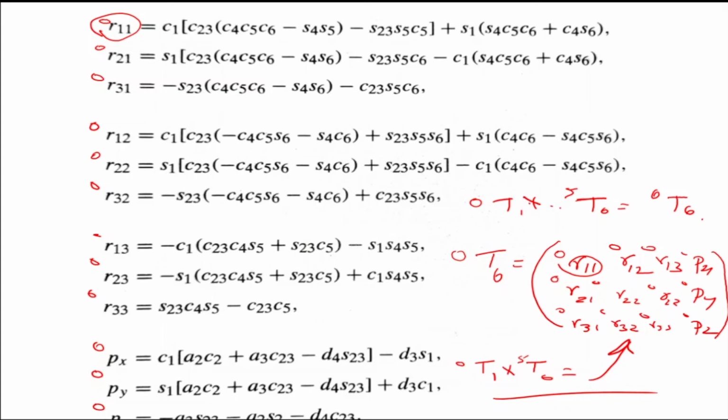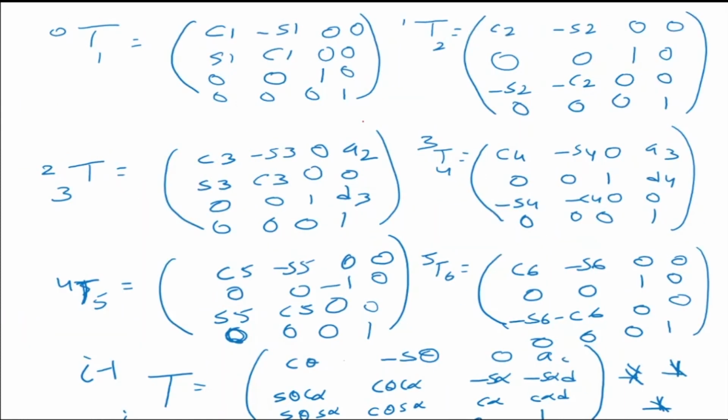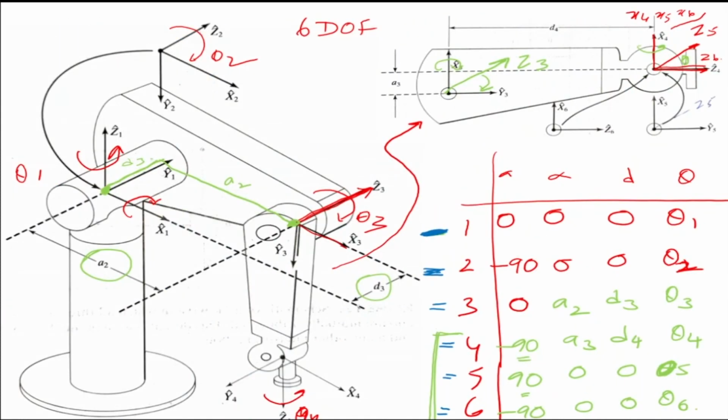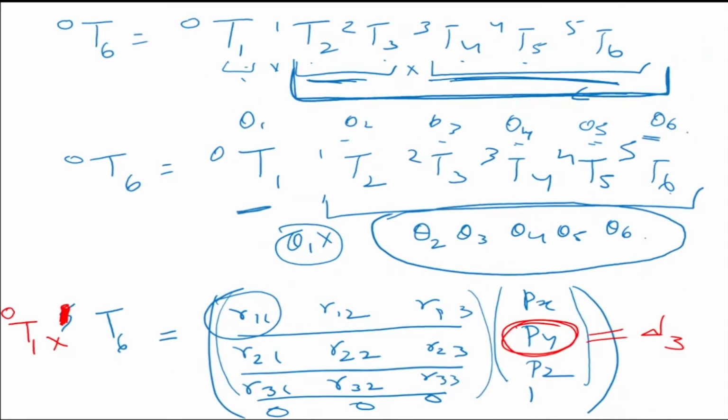Now, why does this happen? This actually happens because of some very interesting properties. When we come to inverse kinematics, we'll look at those. So, for the Puma manipulator, how did we get the final transformation matrix? Exactly the same way. We assigned axes, then we wrote our DH parameter table, and from the DH parameter table, we found the transformation matrices from one frame to the other, using the generalized matrix. Then I multiplied all of them out in a particular way. Now, what was that particular way?